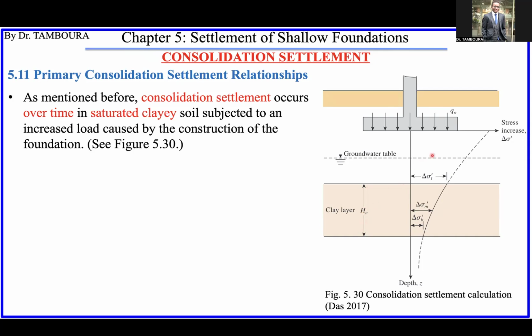And also the stress level, as you know, when you load the ground, immediately at the base of the foundation you have an increase of stress. The effective stress will increase. And when you go deeper, the effect of the loading will decrease like this. But of course, before even loading, you have some stress, right?